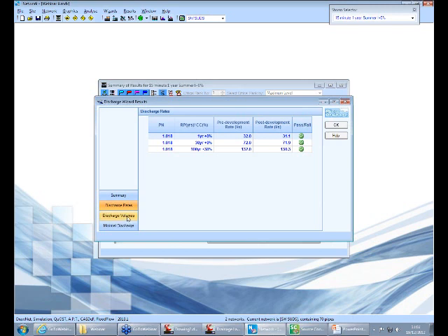How about the discharge volumes, pre and post development? Well, we're now generating 1,186 cubic meters of volume post development. So again, really good job on that, based on applying source control structures, porous paving, basins, infiltration basins, etc., etc.